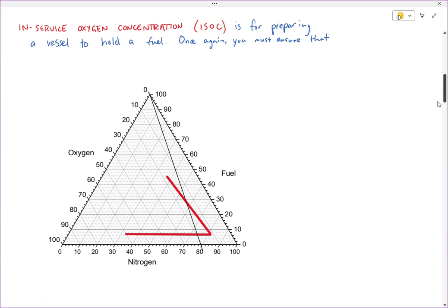I'm going to close it, seal it up, and then start reintroducing fuel into that vessel. So if I do that, again, I'm starting with air. And if I just add fuel to that vessel, I'm connecting it with 100% fuel. Again, look what happened. It's going to trace the exact air line. You see the air line goes through the flammable zone.